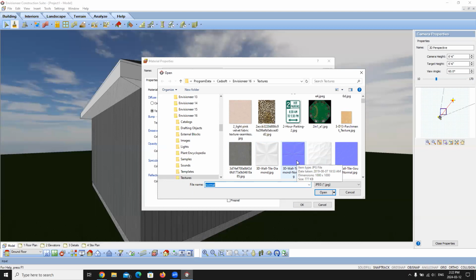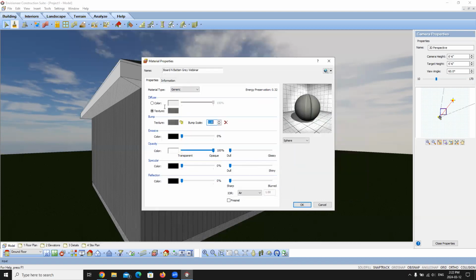Depending on where you're getting your textures from, some textures will have the normals already created, and then you can actually just use those. So you would download not only the texture, but also the normal image, and then you would apply both. What this does is it basically finds the highlights and the lowlights, and it applies that same principle, but using a normal image. And it will give that depth to the actual texture itself.